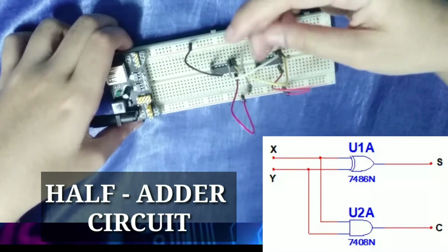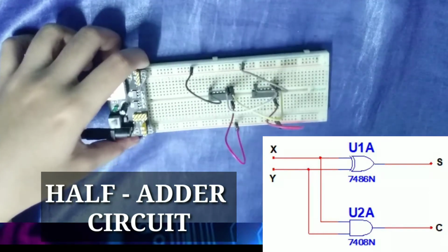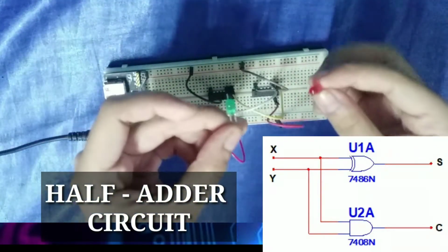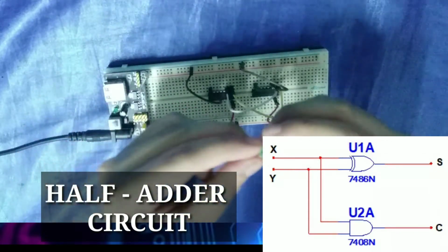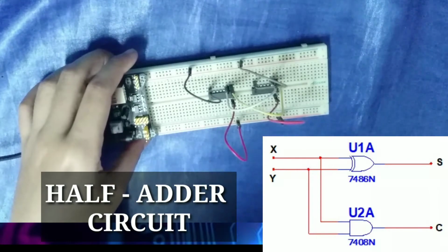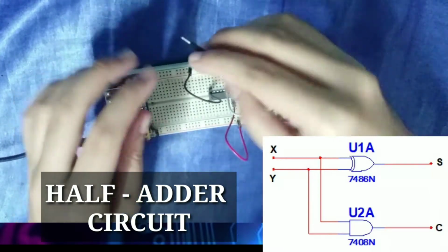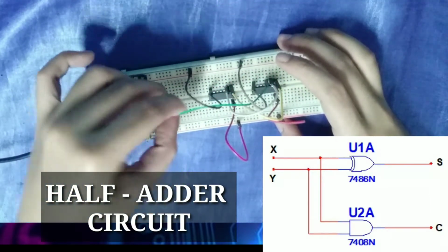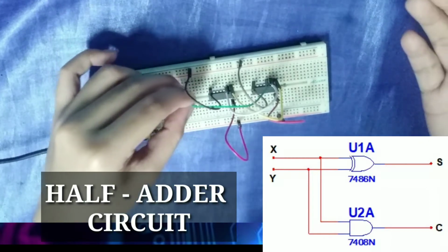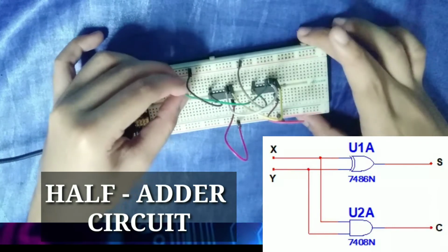And now, for our outputs, we will be needing two LEDs, two color LEDs, which is a green LED and a red LED for our sum and carry outputs. Now, for our outputs, let's connect the third pin of the 7486. This will serve as our output for the sum, which will be from the 7486 XOR gate.